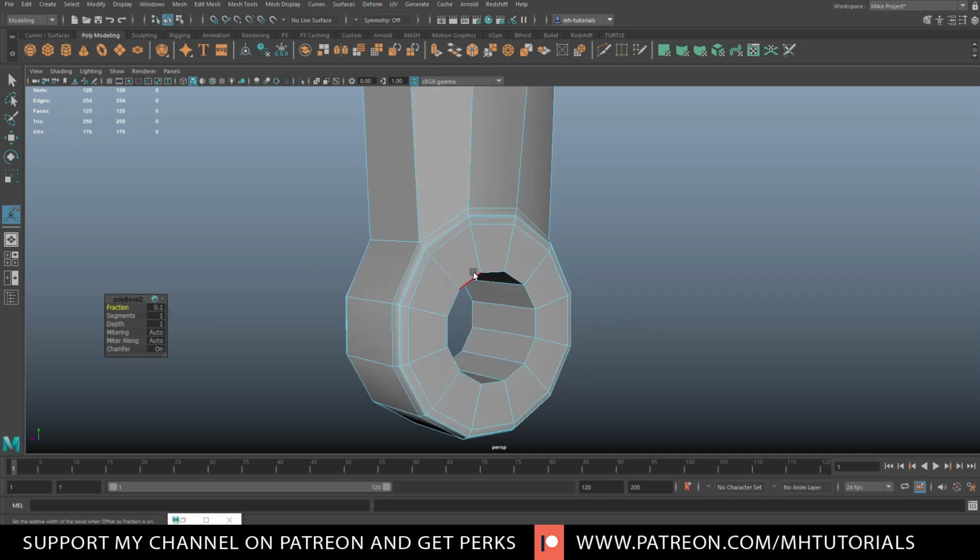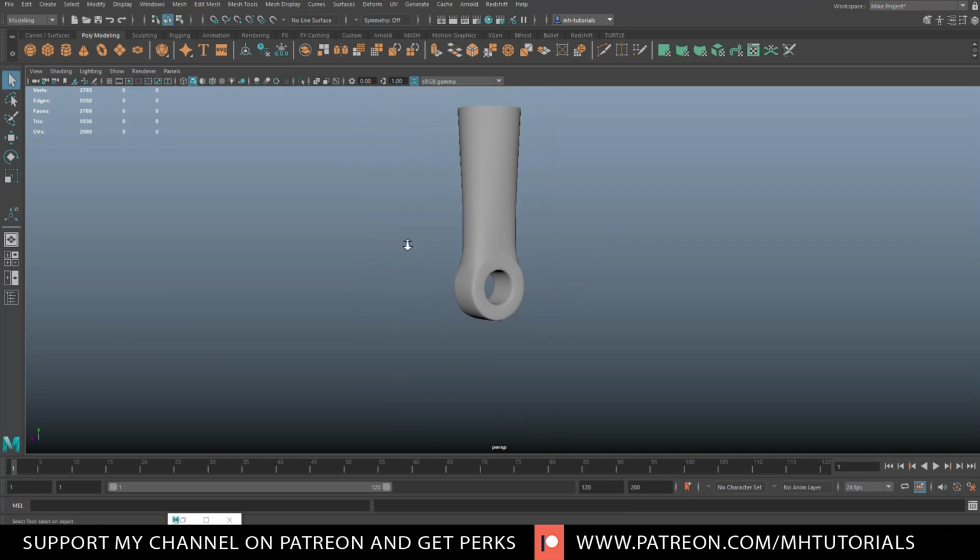And then let's go in and we'll take this guy and we'll bevel that as well, right? Let's do 0.2 on that, and let's do 2 segments on that as well. And there we go. And we'll go to 3 to preview smooth again. That looks a lot better. Okay, nice. All right, good.